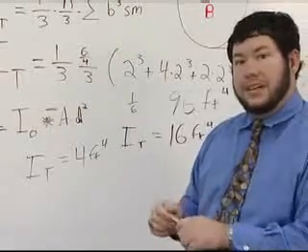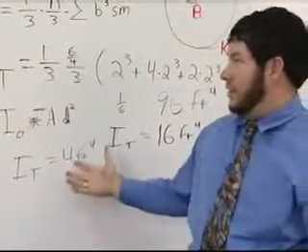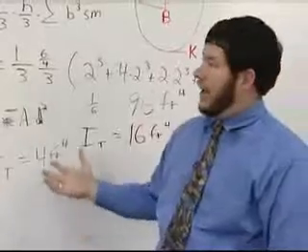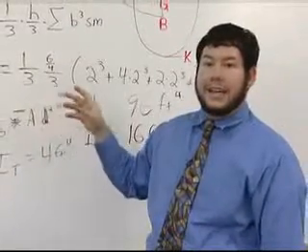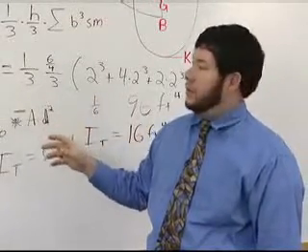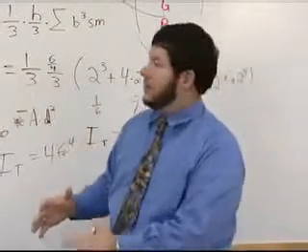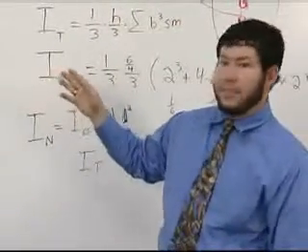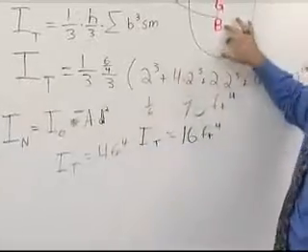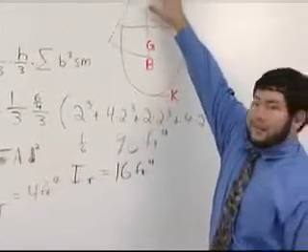So based on using the transverse moment of inertia calculation shown here, dividing by the displaced volume, which we've already calculated in other segments, you can arrive at BM, or the distance from the center of buoyancy to the metacenter.